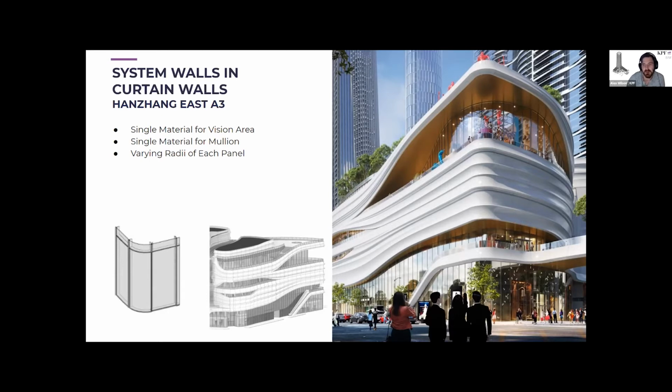This allowed a couple of great things. The first thing, wall sweeps obviously follow the wall, so they're going to be curved. They're not going to be faceted. Second, it allows you, in a certain way, to create a type parameter for the mullion location. It allows you to set the wall sweep height based off the wall itself instead of as an instance parameter, which is the downside of using system panels instead of loadable panels.